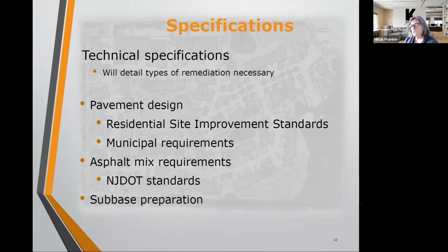So DOT has these standards for the types of asphalt that should be used, and it's generally what the mills produce. In the past, for residential use, there was what was called the Marshall mixes. Now we have what has sort of a nickname, Superpave. They're the same materials, but they're a different type of mix, and they are just a little more brittle than the older mixes because they have a lot of recycled asphalt product in them. It's just what's available now.